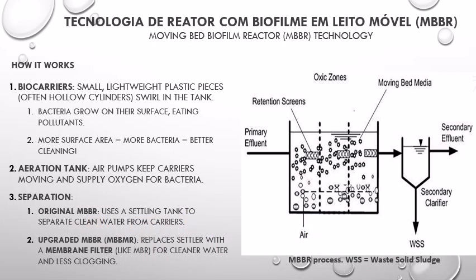Next, moving on to the biofilm reactor technologies, we have the moving bed biofilm reactor. This is the MBBR method. It acts like a biocarrier. These are small lightweight plastic pieces, often hollow cylinders.